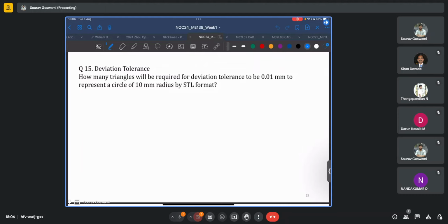Last week, we were introduced to additive manufacturing terminology, and we got an overview of all the basic processes. Also, we started looking into how the exact geometry of a solid is converted to STL files, how the representation is always an approximate representation, but with smaller triangles and finer mesh sizes, it tends to the exact approximation.